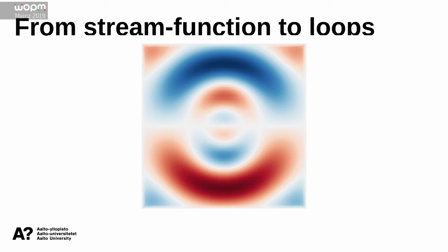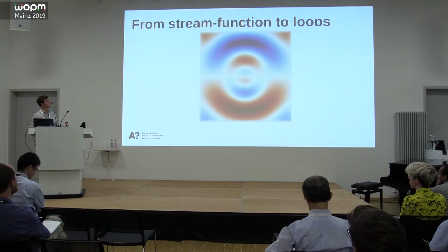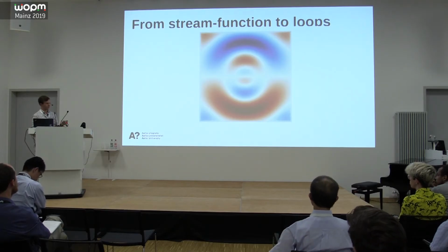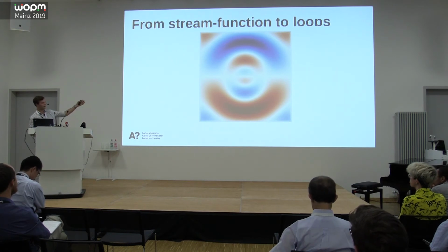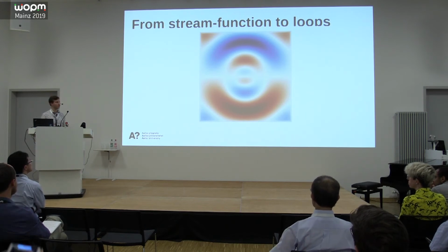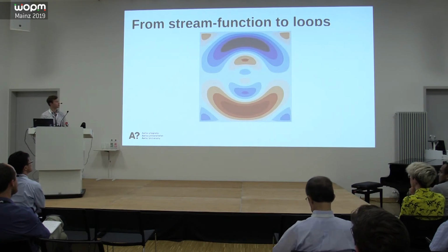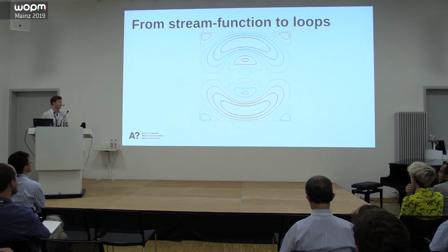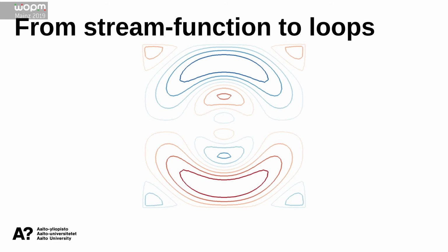So this S, after running this quadratic optimization, is what it might look like on a coil surface. This is the surface current, or the stream function S, rather, and this would create a field behind the projector in the Z direction, the vertical direction. So how do we go from this to actual coil windings? Well, you do this. Just take the contours at a set number of points, and then, you might see where this is going, like this. And these are now closed loops.